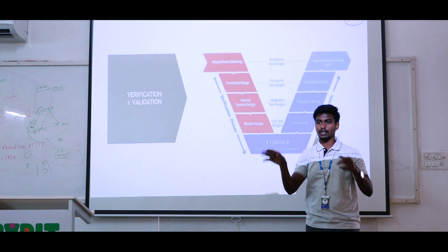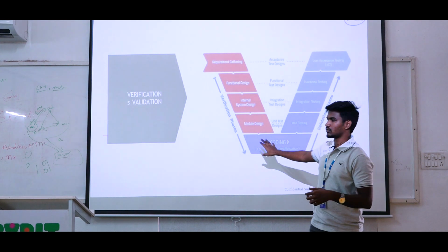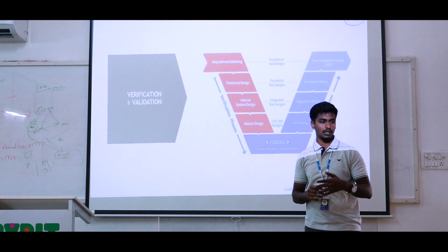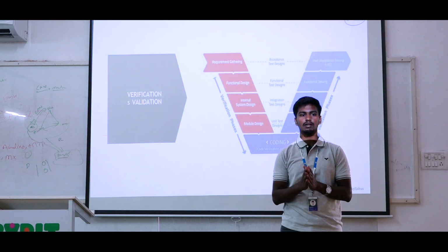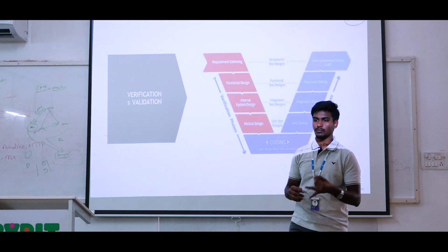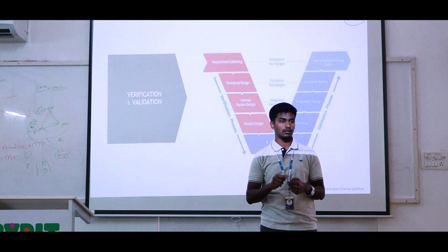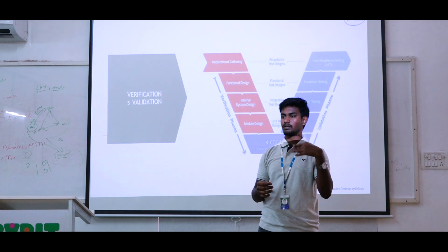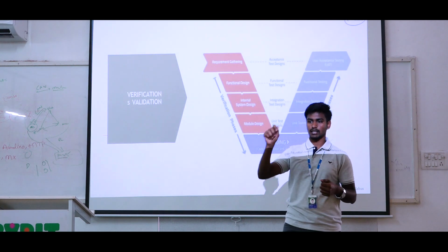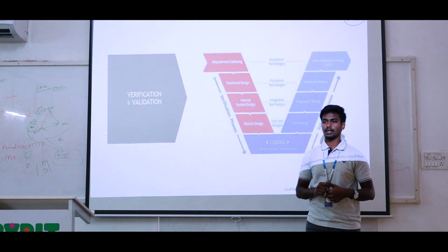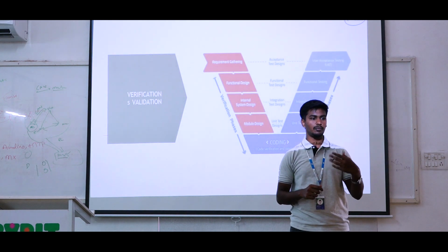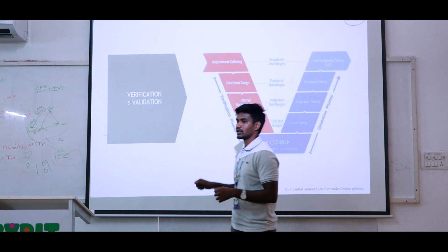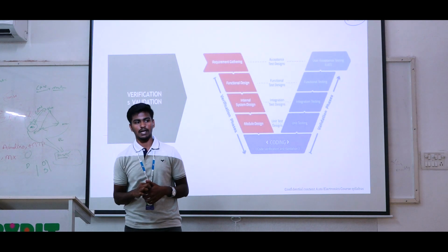This coding part is covered by our ECU CAPL scripting. Based on the coding, the testing will be conducted. If this testing passes, the feature will be enabled in our ECUs. For that, they write some programming and also a flashing program. If that program gets any fault or error, UDS will be used to access it. With services like 0x34, service 0x36, service 0x11, based on those services it will reprogram our ECUs. That is called ECU flashing or ECU reprogramming. This is the important way of testing our software, called the verification and validation method.